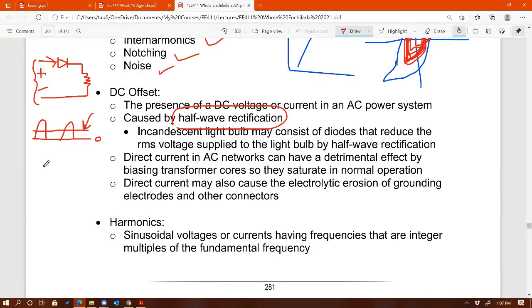And this current comes from a transformer, comes from the distribution transformer. So imagine if this current comes from here, right? But luckily, the transformer is blind to DC, so it will shift that down to that kind of current there on the primary side. But nevertheless, this DC offset, when it gets so high, it could be damaging to this transformer. But on the primary side, it's safe because, again, an inductor is blind to DC. It's just going to be a short to a DC. Okay.